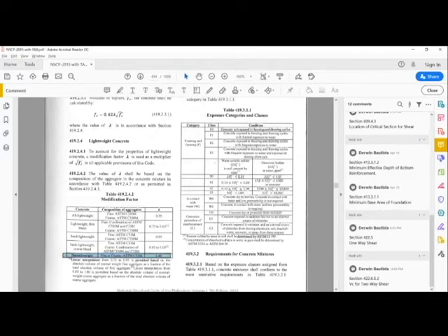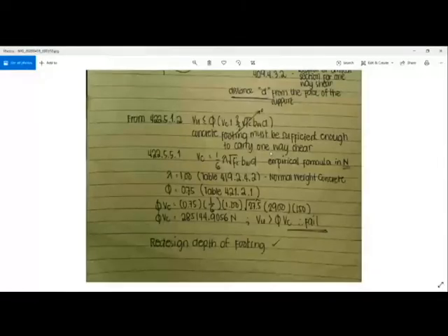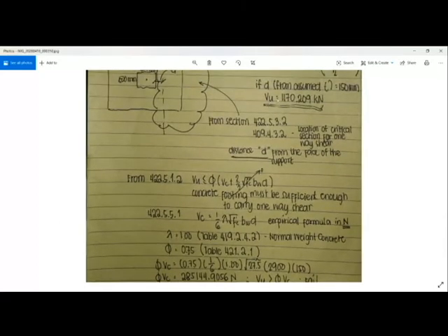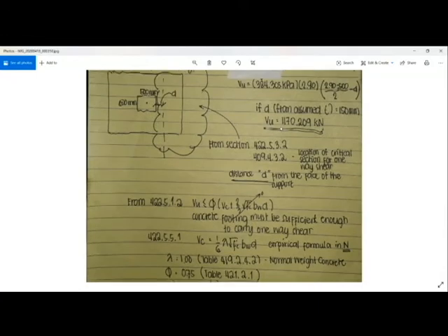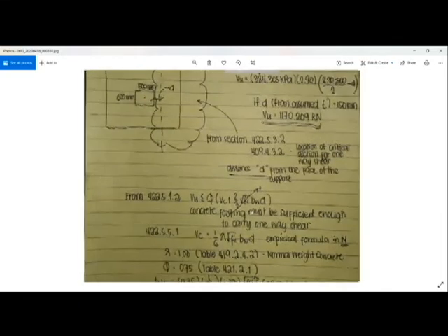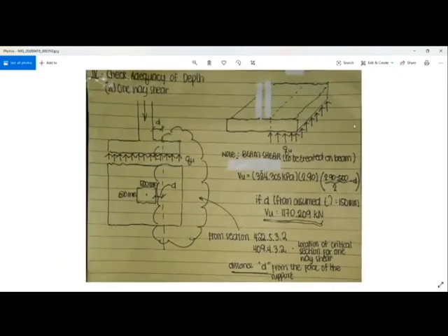Okay? I assume that you are already familiar with the formula from the code. So ang lumabas natin, when we decided to compare, your Vu, yung computed Vu natin, which is equal to 1170.209, and your phi Vc, phi is equal to 0.75 multiplied by 1/6 times 1 times square root of 27.5 multiplied by 2,900. 2,900 is the base here, this one.